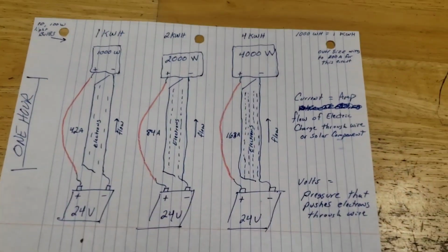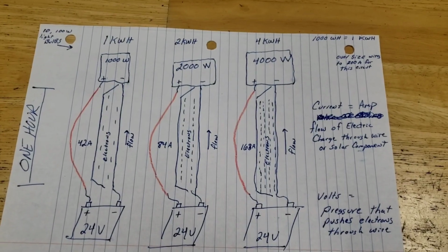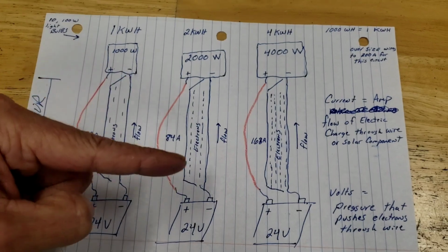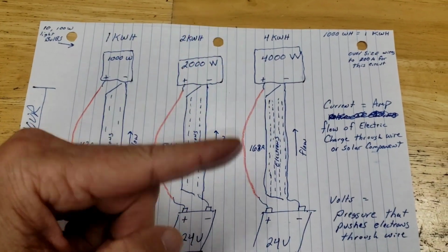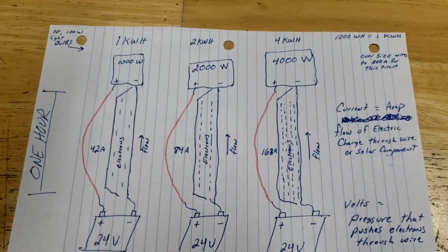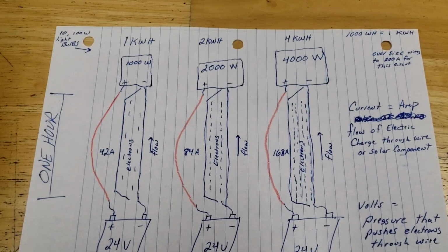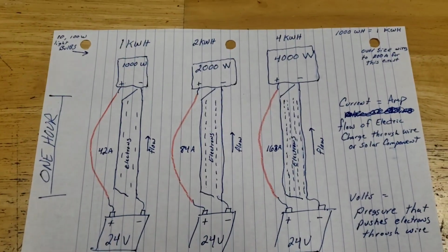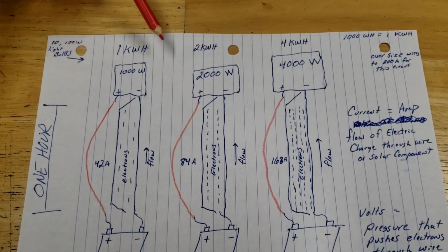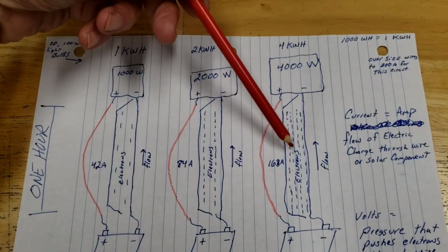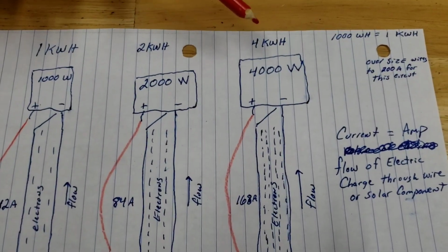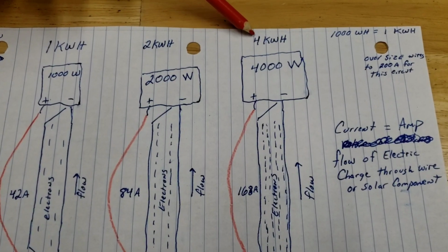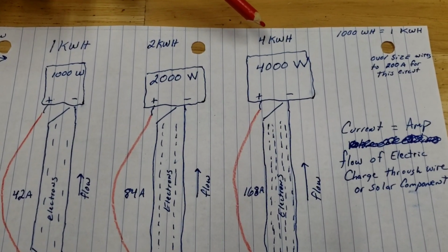One thing one of the guys did mention to me, being that this is wire, not hose, we're still carrying electrons through that wire. If we're building a solar system or even wiring our house, and these are the loads, you need to make sure the wire you put in can usually handle 50% or double the highest load you have.